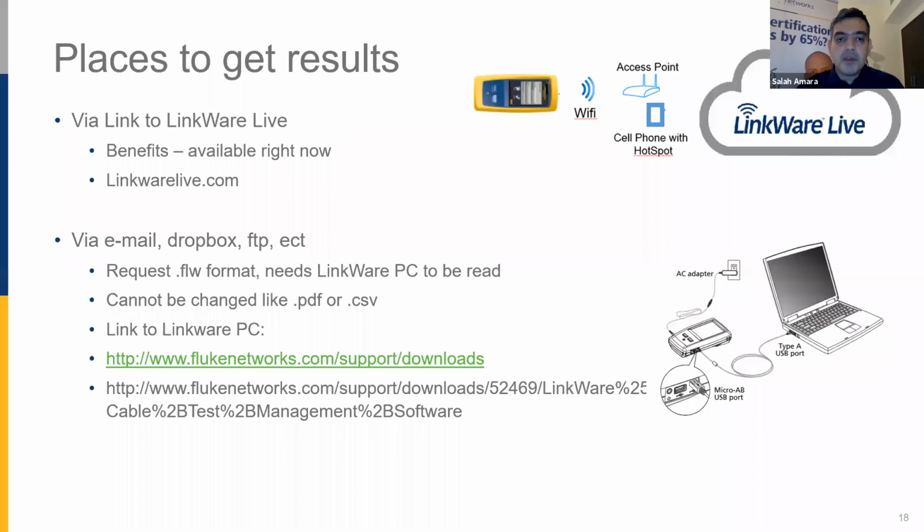But a big request for you is always to ask for the result in the Fluke original format, which is the FLW format. We will talk in more detail about why we need to do that, but simply because, as we know, there are a lot of sophisticated softwares that can modify PDF reports, but there is no way to modify the results that you receive in the original Fluke format, the FLW format.